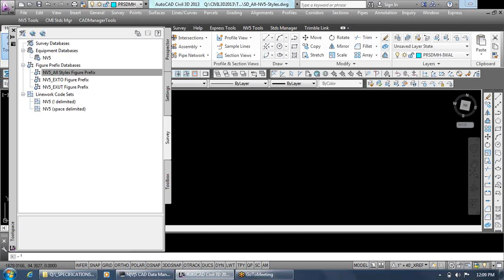The other item that can affect the undo is using the mouse wheel button to zoom and pan. That can also cause problems with the undo command. I don't have a good workaround for that because we all use the mouse wheel very wildly. Question: if it's a known bug, why doesn't Autodesk fix it?